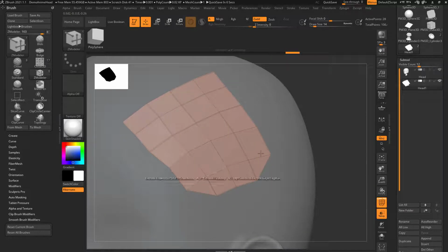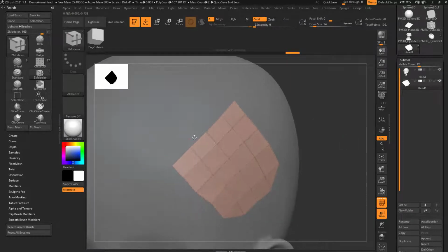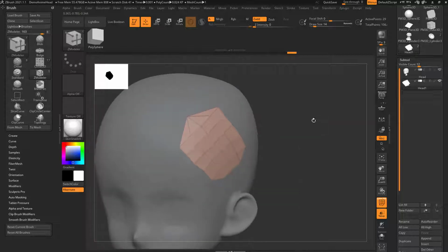and snap these. And you can even do triangles. So if I hover over a face, or hover over an edge and do extrude here, and we'll just tap Alt once so we pull out a single edge. I can grab this edge, and as I pull to the side here, I can actually snap this to a triangle. Same thing with this one. You can just continue snapping to triangles if you want. Or you can go through here, move, and then snap to a single point.